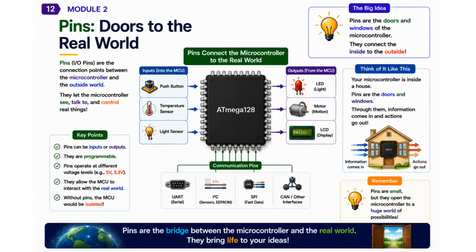Other pins are used as outputs. They allow the microcontroller to control external devices. An output pin can turn on an LED. It can drive a motor. Or it can send information to a display so that users can see important data. Many pins can also be used for communication. They support interfaces such as UART, I2C, SPI, and even CAN networks. These communication channels allow the microcontroller to exchange information with sensors, memory devices, computers, and other controllers.